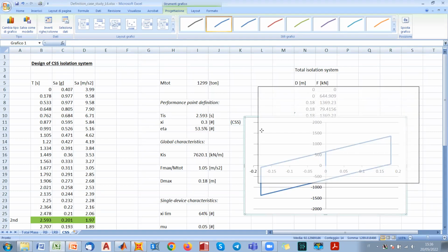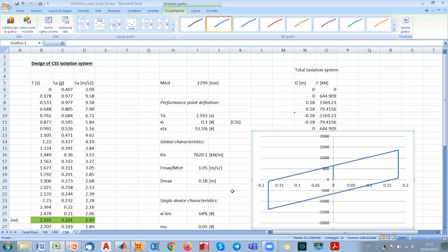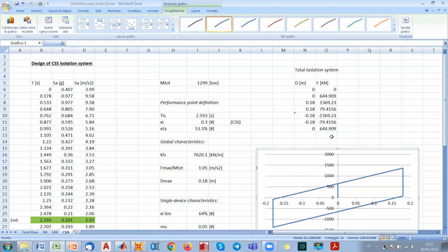And then you can do this also for the lead rubber bearings and the rubber bearings. I mean, for rubber bearings with and without the lead core, I think that the best solution is to do exactly the computation continuously. So similarly to what we modeled yesterday, with the sinusoidal waveform for displacement, and then with the hysteresis rules that we computed for the single degree of freedom, but not for time integration, just for representation of loops. The curved surface sliders can be simplified like this. I mean, it is very simple.